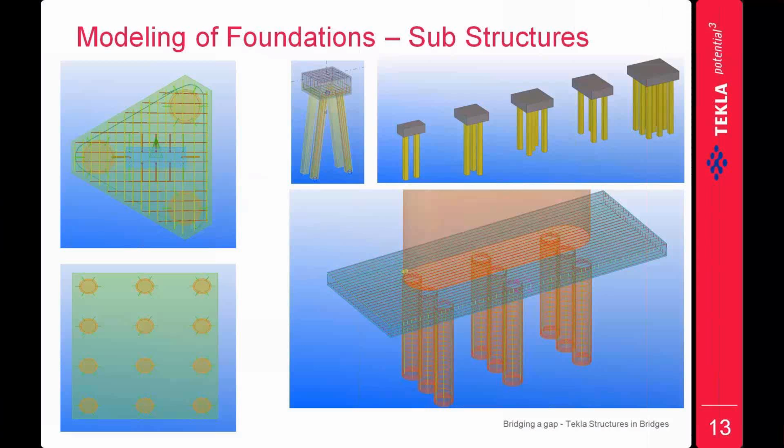When we start with the project, definitely the first part we are going to do is the foundation side. That is the substructure, where we have different options available. These we call custom components. With just 1 or 2 clicks, we will be able to model the concrete part as well as the reinforcement for this foundation. Say, for example, starting from the 2 pile cap or 3 pile cap up to 12 pile cap, or the straight or the splayed one, even the mat foundation with the piles. So the different arrangements are readily available, so that very quickly we can model the foundation for the bridge structure.